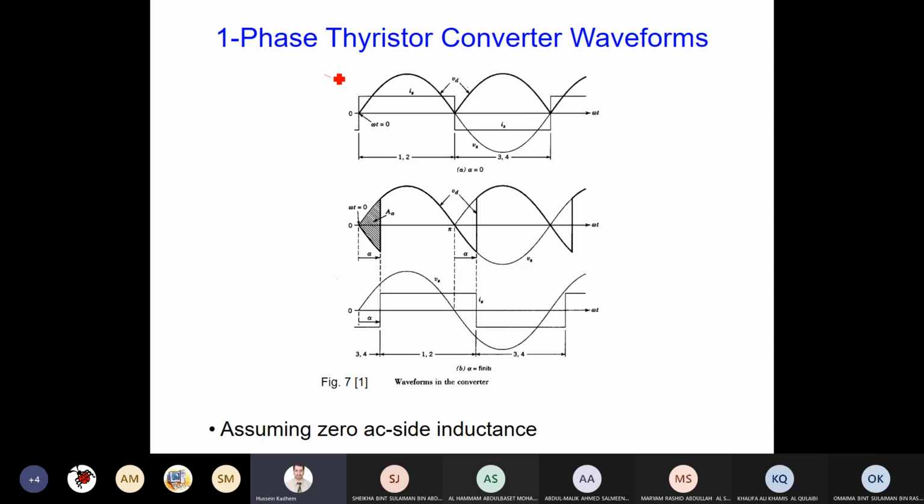This is the waveform discussed in module 1. As you can see for the diode, the input signal, positive is okay. The negative signal will be rectified to become positive again. We rectify this one here, as you can see, and the output starts at the same time as the supply. There is no delay.